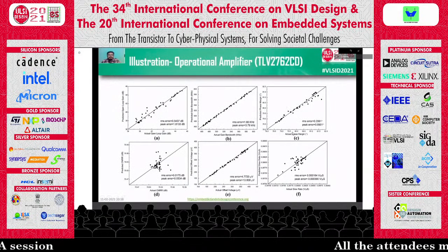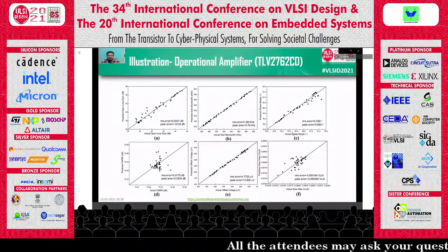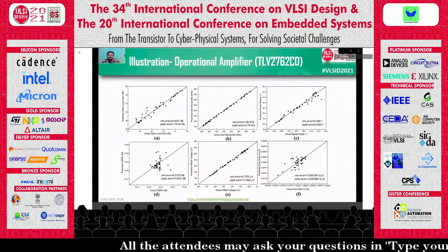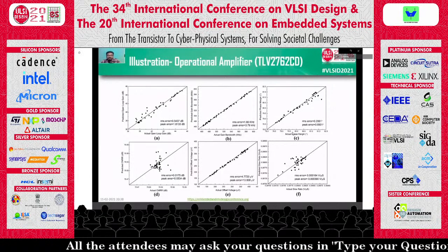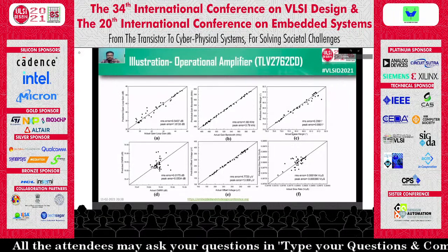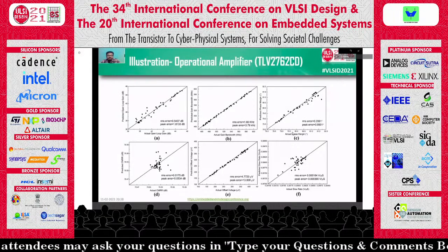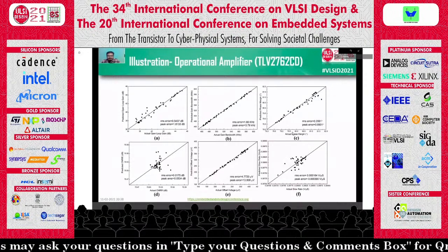The proposed technique is also validated for a commercially available IC, TLV2762CD by Texas Instruments, for the same performance parameters using the same test stimuli and circuit configuration. The 45-degree plot among the simulated and the predicted values shows the accuracy of the algorithm for practical IC specifications.